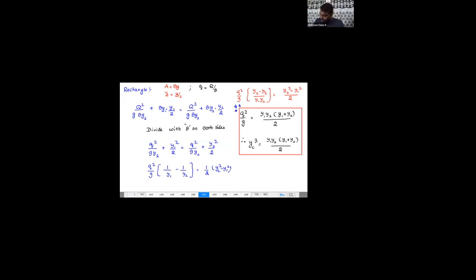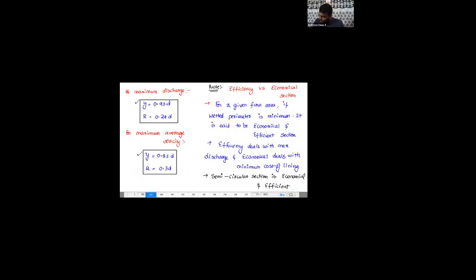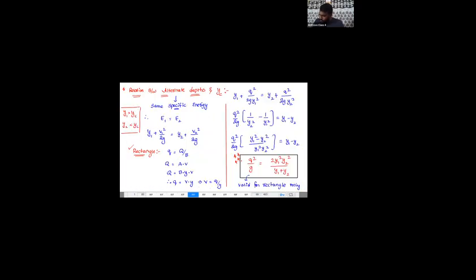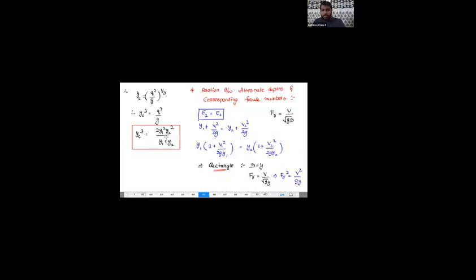Now let's go back to the alternate depths. Here, this is an alternate depth, and what is the type of channel I am taking? Rectangle. And what is the equation I got? Q square by g is equal to 2 y1 square y2 square by (y1 plus y2), where y1 and y2 are alternate depths. Q square by g is nothing but yc cube.